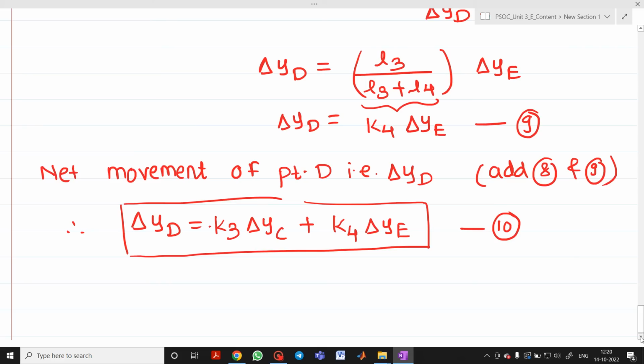We know that as there is a movement here of point D and point E, either in an upward or a downward direction, there will be some inertial reaction forces. So whatever inertial reaction forces of the main piston and the steam valve, let us consider that it will be negligible compared to the force which is exerted on the piston by the high pressure oil.